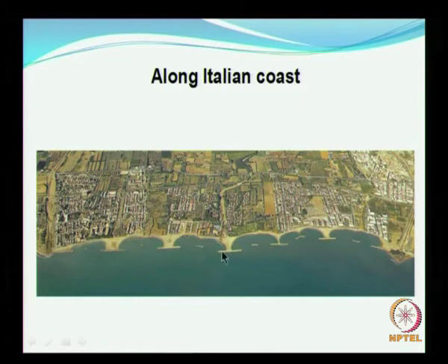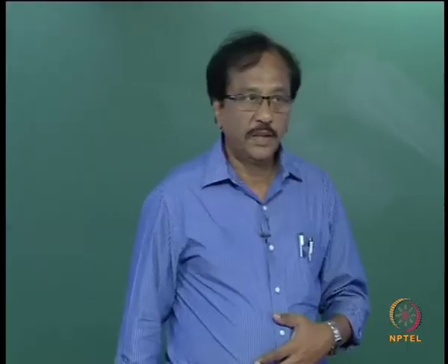If you think this bay is quite wide and you want to reduce its width, you can still have small structures parallel to the coast, and that will trap the sediment. So you will have a reduction in the bay size, you understood. This is the advantage of offshore detached breakwaters.